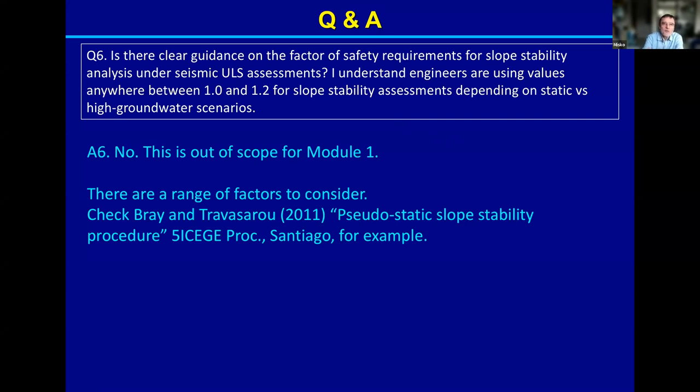if you're getting flow type of movement or large deformation. And finally, the meaning of this factor of safety also has to be put in the context of how good is our estimate. One thing is for sure: whatever slip surface we have assumed, it is not going to be the one that is going to fail in the future events. So in that sense, this 1 or 1.1 and 1.2 are proxies in the assessment.